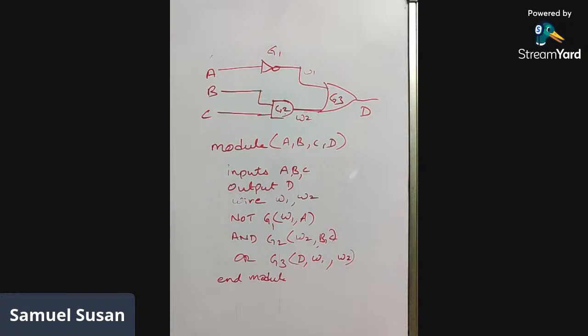Important question. That is what we are discussing here. When you have that bar, you can take it as an XNOR multiplied by A plus B, right? Even if it is AB' plus A'B, when you perform a complement to that, you get A'B' plus AB, and you are multiplying that with A plus B. So finally, you are left out with again A plus B, right? So are there any doubts in these K-maps or don't care conditions? Then we go with it.